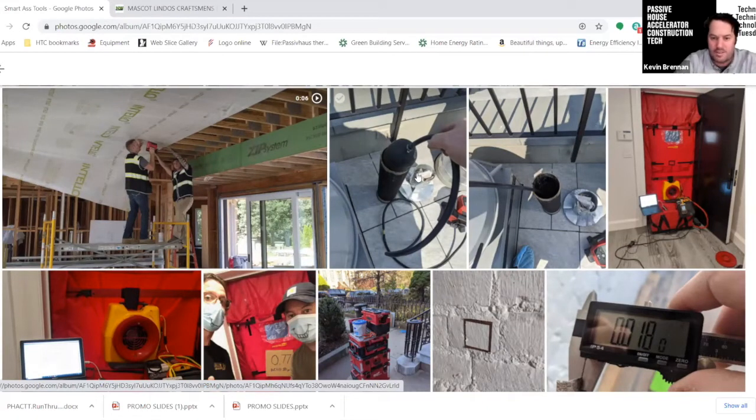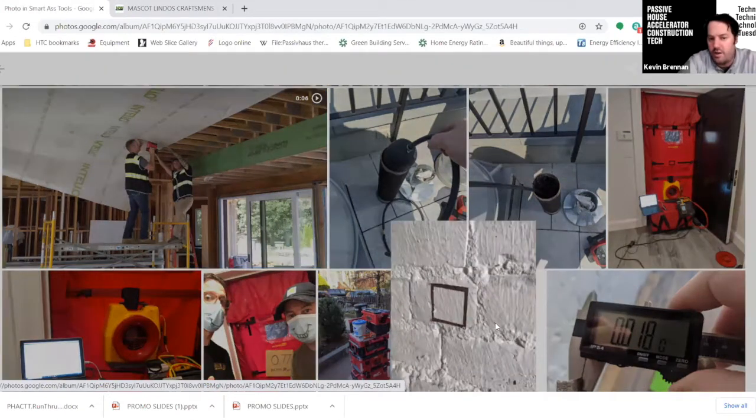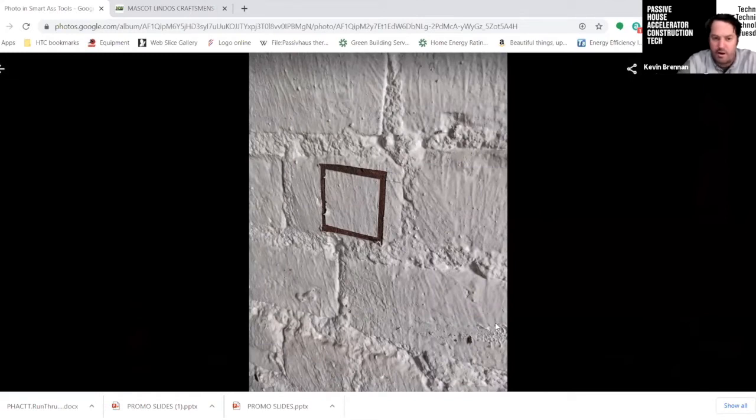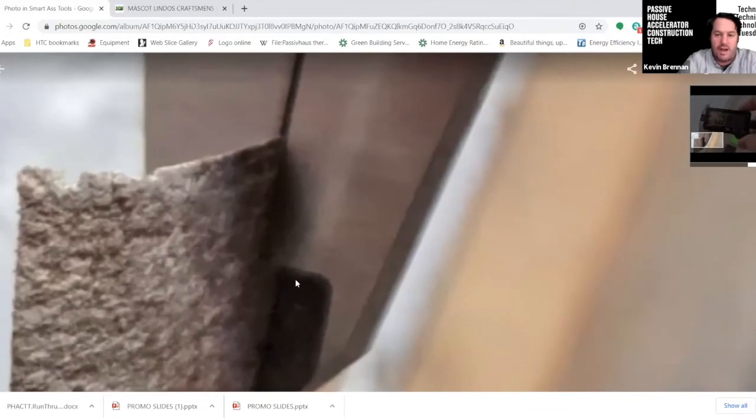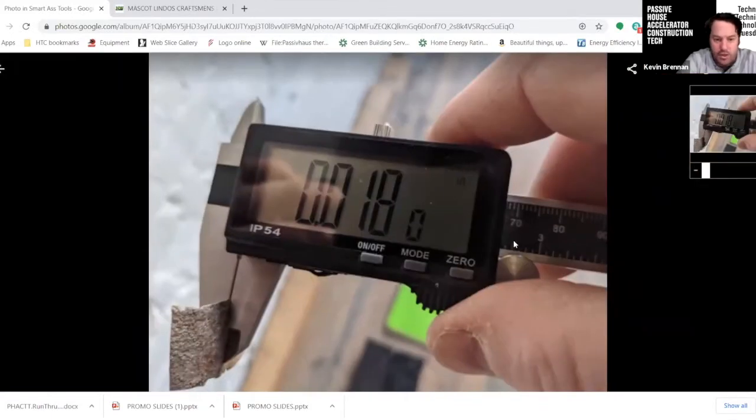I had to order them from Amazon UK, and I waited forever. And then the last tool that I'll really show, because the fluid applied air barriers is what we covered last time, is this. After the membrane has been installed, we cut around the outside, and then you slice it off with the knife. You make sure that it's scraped off, and you come up with a sample, and then you measure the dry mil thickness in 1/1000th of an inch of how thick it is. And then working with the manufacturer, you would then find out how thick you need it to be.